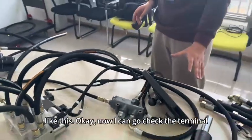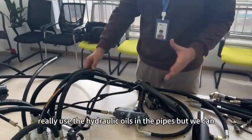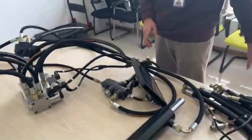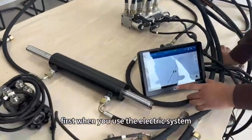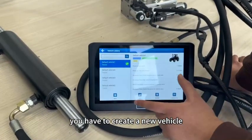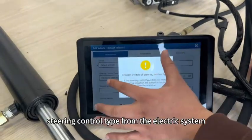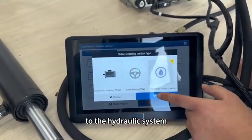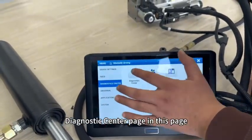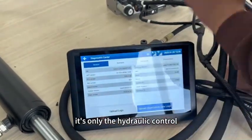Okay, now I can go check the terminal. There is no real hydraulic oil in the cables, but we can show the lights on the terminal. First, when you use the electric system, you have to create a new vehicle and then click edit. You have to switch the steering control type from the electric system to the hydraulic system. Click OK. And then you can check in the diagnostic center page. In this page, there is no longer a motor version here, it's only the hydraulic control.